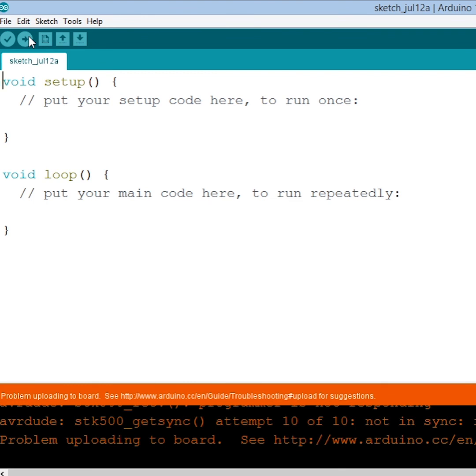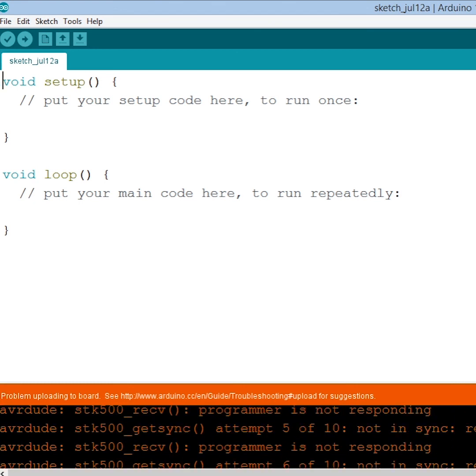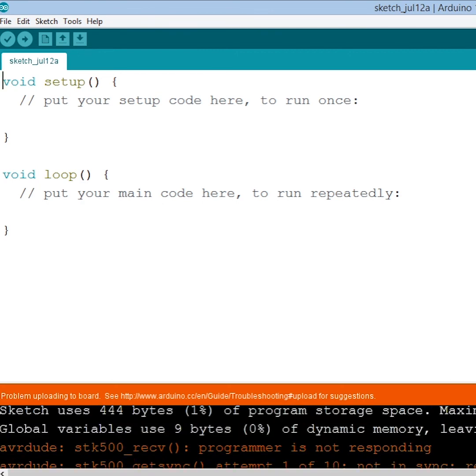These are the two or three common types of error that we're gonna find while using the Arduino board. What we have to do is just make sure that in our settings we have selected the right port, the right board, and the right programmer. If all of these are checked, we are sure not to get any errors.